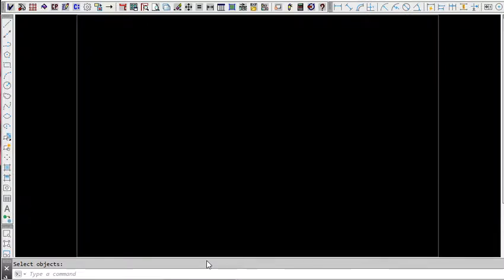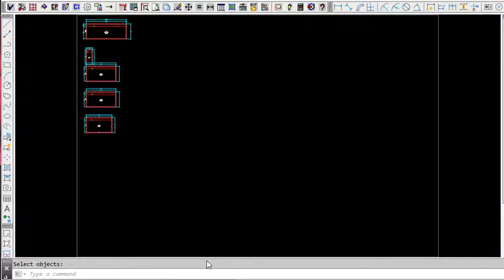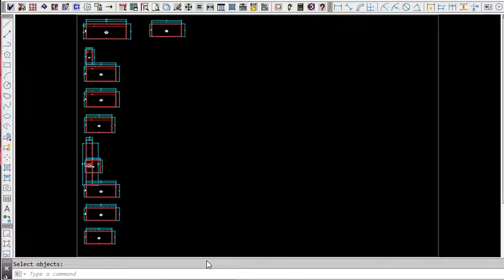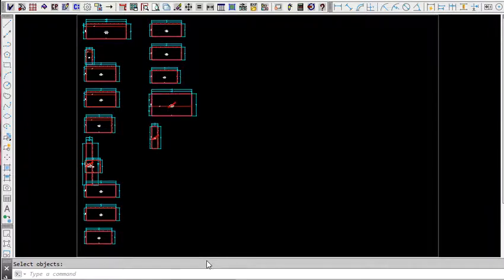And so down in our draw flat panel work zone, it's going to start laying out these panels. And sometimes it's just the way AutoCAD is. So that little panel that turns sideways like that, that's because the grain is going north and south, and that forced the panel to be drawn in that direction. You can always go back and modify individual grains and stuff like that. And it looks like one of the panels is kind of screwed up, so we'll ignore that right now.